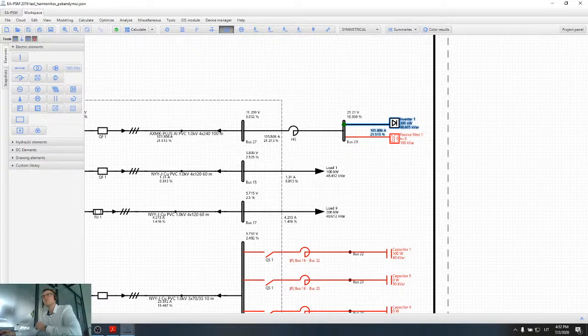If in the UK you have this kind of requirement, it depends on what reasons you have for this requirement and why you need to calculate this. Higher frequency harmonics, like the 100th, would be 5000 hertz harmonics. They affect communication lines more, and in our software, because we do calculations of power networks, these very high frequency harmonics are not that important.